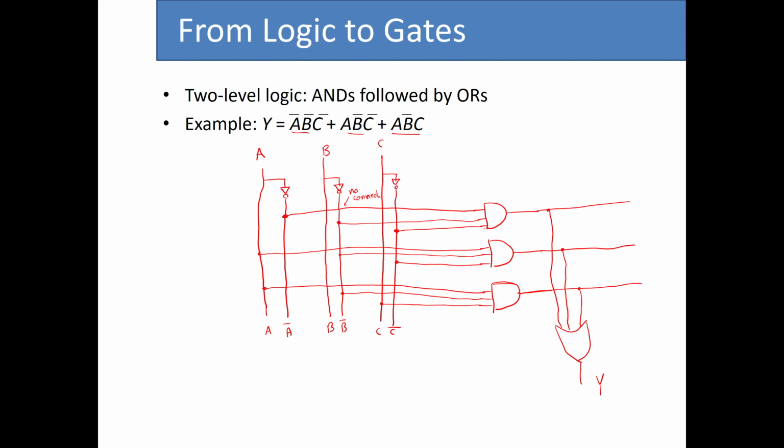And this can preserve the logic that we follow to come up with the equations, for example, using sum of product form. If we had a function that was in the product of sum form, all these gates would be OR, and this one would become an AND gate. So this one is for a product of sum.